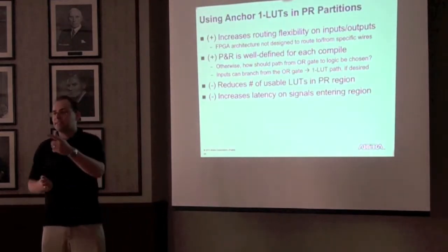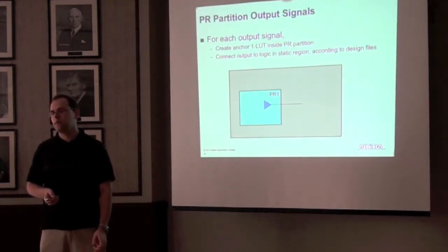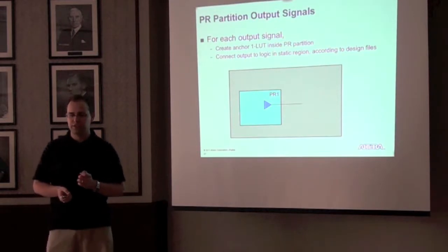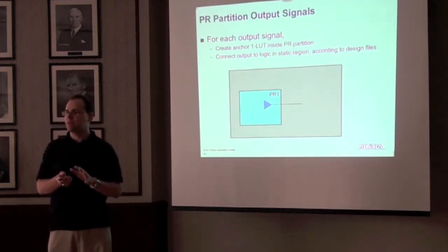So, yes? Sorry, are these anchor LUTs placed in a way that you can guarantee that that's the last LUT to change when you're reconfiguring a region? That's so that it kind of acts as the signal to say this region has now been fully reconfigured. So that's a good question. So does this anchor LUT act as the last one to be reconfigured? Is that the question? Yeah.